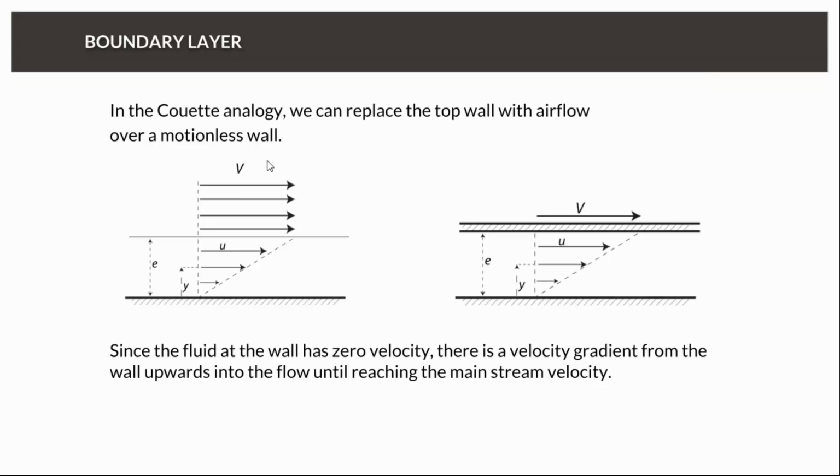So when we are far from the disturbance of the body, the air will have the same properties as the uniform flow v. And we still have the condition of zero velocity at the wall, or the same velocity as the wall has. As the wall is stationary, we will again have speed zero at the wall. That means we will have a gradient of speed, a variation of speed of the air between no speed at the wall and the external speed, far enough from the body.